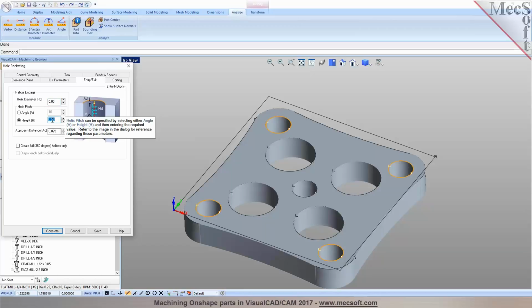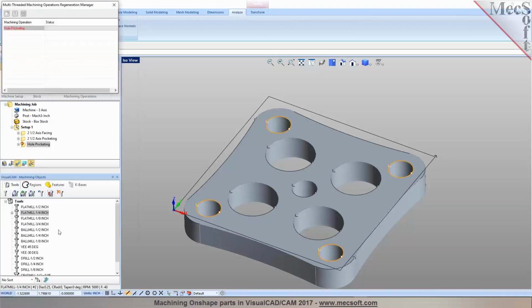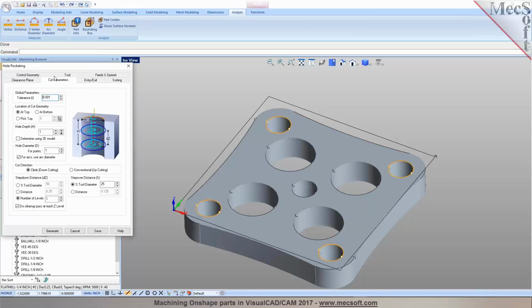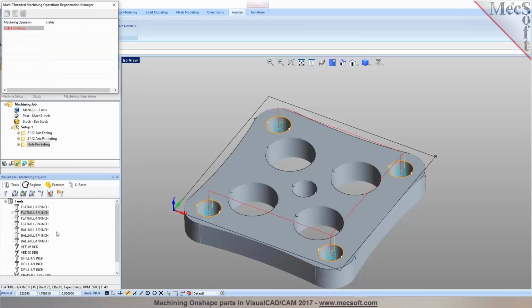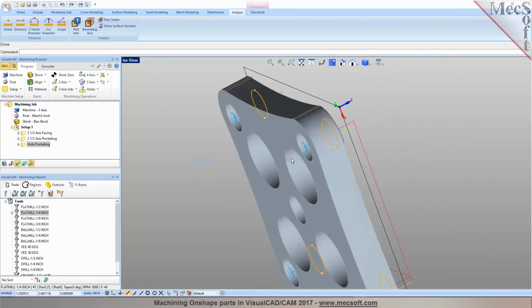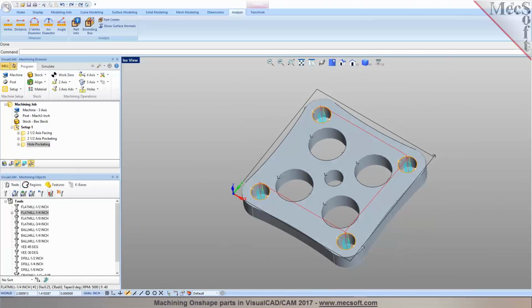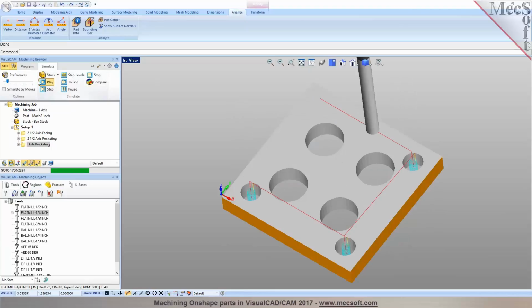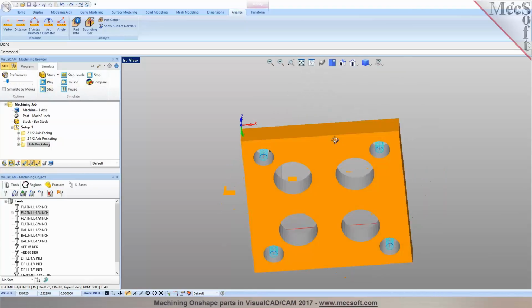So you can do a helical, the helix diameter. And you can specify the helix pitch in here. And if your controller can do helical interpolations, G02 or G03 with X, Y, Z, I, and J, we could do that as well. And here I just put in my depth, which is 0.4. And you'll notice the toolpath creates a cleanup pass at the bottom of the hole right there. So it's doing a helical interpolation, a helical cut pattern.